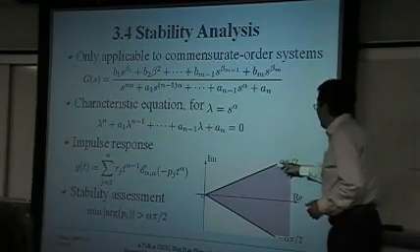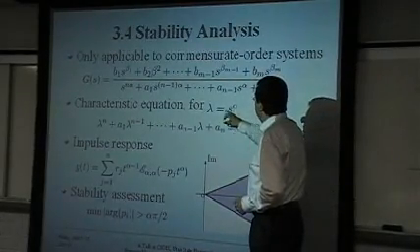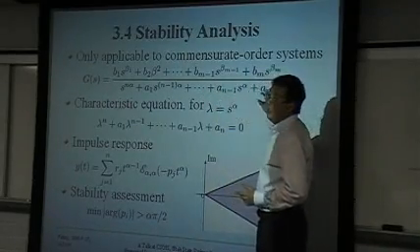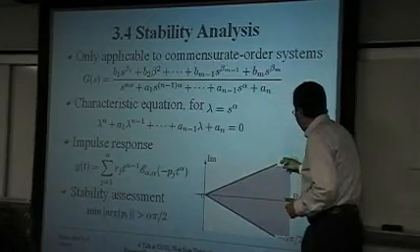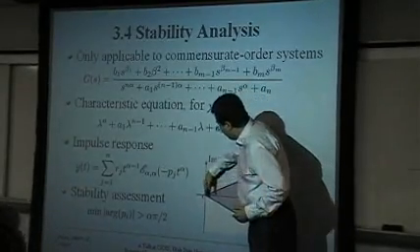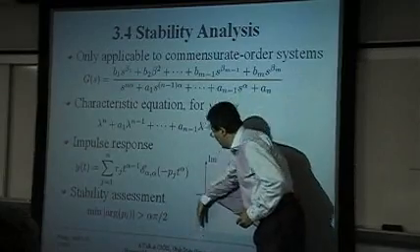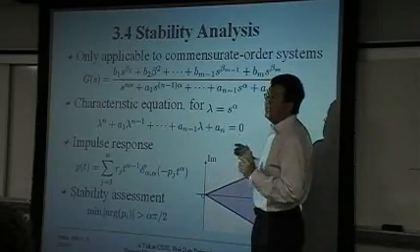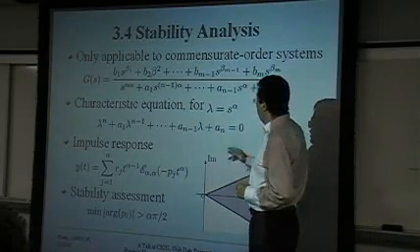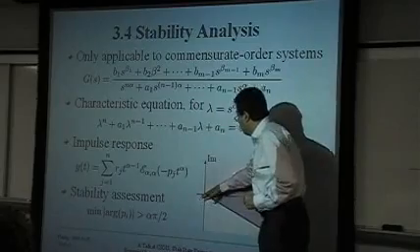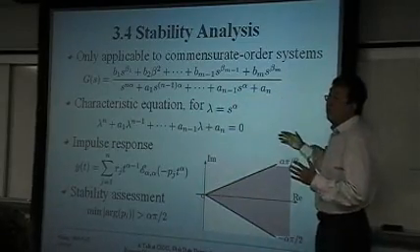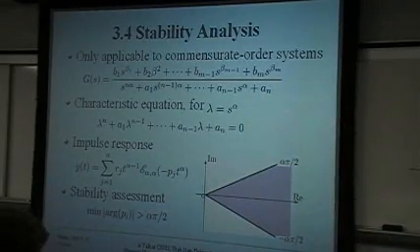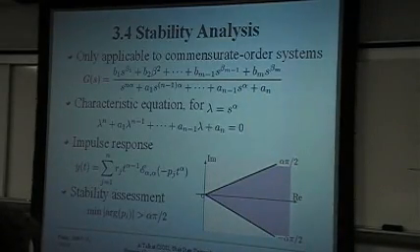If alpha equals 1, we see that lambda equals s, and it is an integer order system. And for an integer order system, when alpha equals 1, this line will be changed to a vertical line, which is the imaginary axis. If all the poles are on the left-hand side, it is stable, otherwise it is not stable. However, for fractional order systems, we must use a line like this to distinguish the stability regions. So this is the stability analysis of the system.